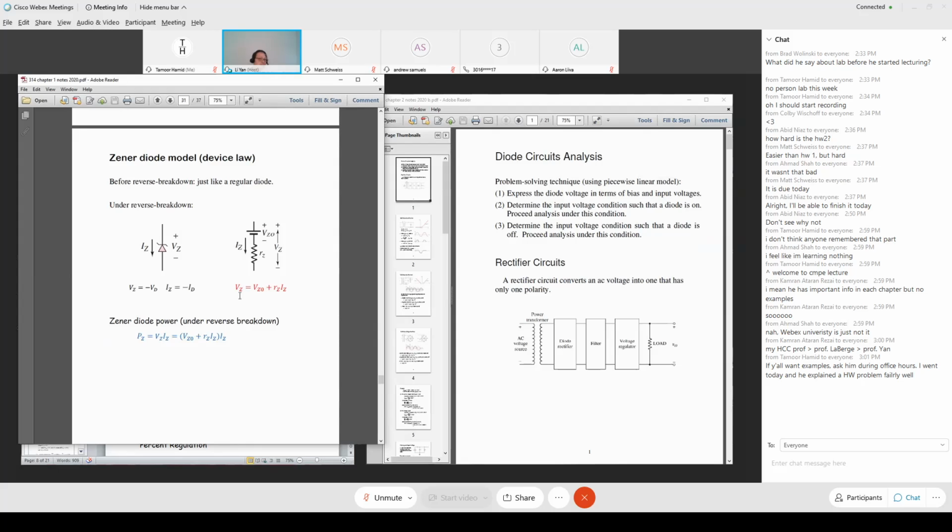Exactly described by this formula. And this formula means what? The full Zener voltage contains a constant step breakdown voltage VZ0 plus, if we visualize there's a Zener resistance in series with this step down voltage, then there's additional voltage drop by Ohm's law by the second term described here. Are you clear? That's a realistic Zener diode.